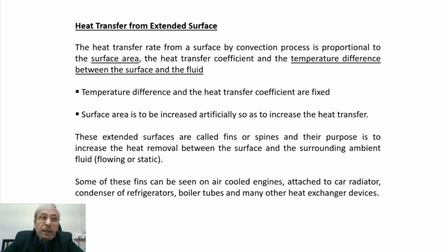So there is an effort to increase the surface area so that the heat transfer is enhanced because of enhanced area. So, as we have already said, the heat transfer coefficient and the temperature difference for a given situation are fixed. So these extended surfaces are called fins or spines, and their purpose is to increase the heat removal between the surface and the surrounding ambient fluid.